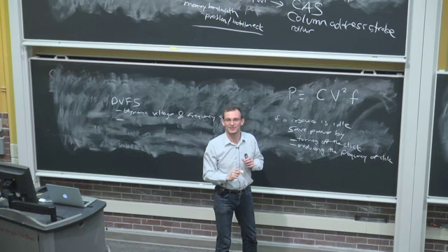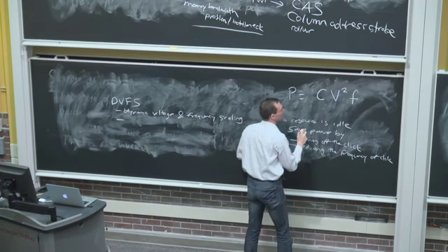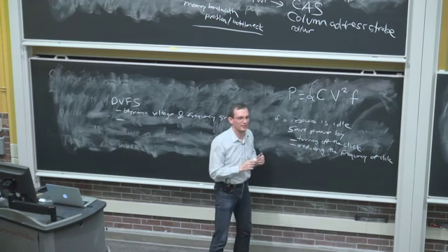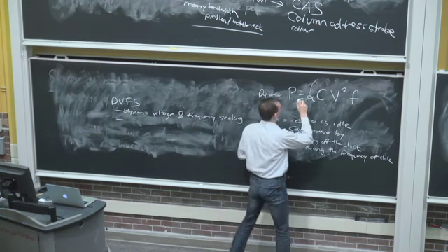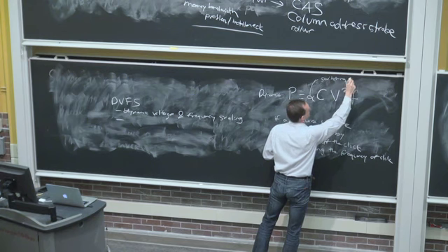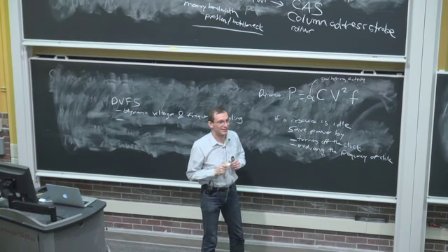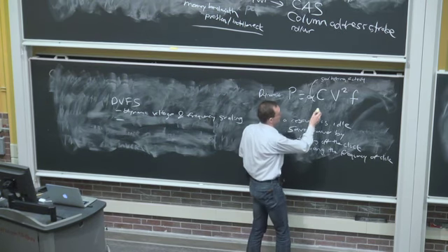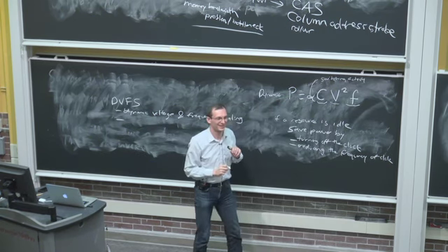Does that make sense? Have you guys seen this before? Some of you have. Okay, voltage squared and frequency. And there's also some factor. This is how active. Let me call this the dynamic power, actually. This is the switching activity, if you will, in the circuit. And it depends on whether you switch the data, whether you switch the transistors. So obviously, if you want to minimize power, you would like to minimize all of these.